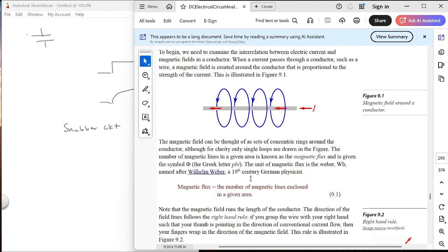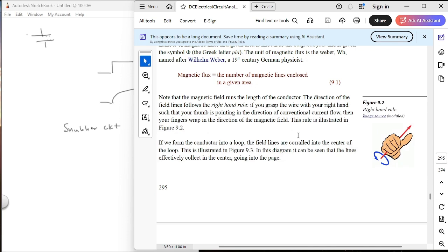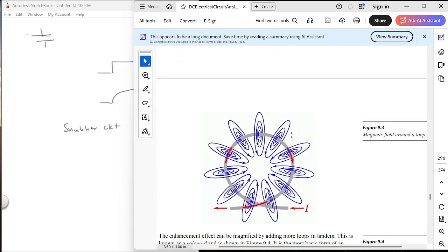And that's why you lay wires in a trough or something like that. You only put high voltage wires, or you don't put analog wires in with a bunch of motor wires, because they will crosstalk, and this will crosstalk to those other wires and give false signals. So again, these are things that you don't think are important, but in some cases they're very important.